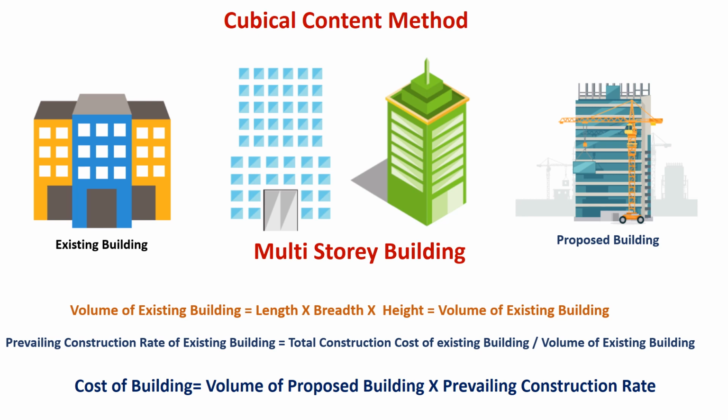So after getting the construction rate of the existing building, you can calculate the cost of the proposed building. By calculating the cost of the proposed building, you multiply the volume of the proposed building, that is length, breadth and height multiplied, into the prevailing construction rate.